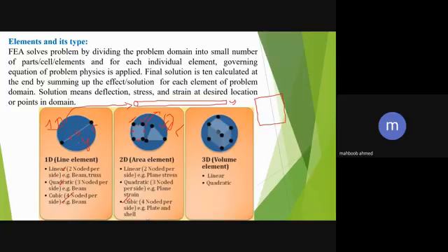First you decide whether you are going to use 1D, 2D, or 3D, and then you have to decide what type of element: linear, quadratic, cubic, or even higher order. But remember always, as you go higher, your computation time will increase, because the number of equations to be solved will increase.